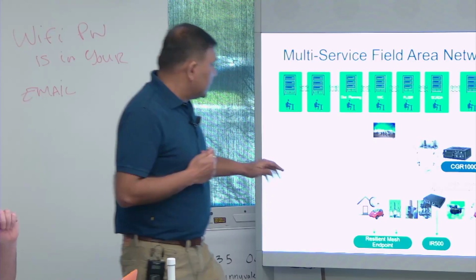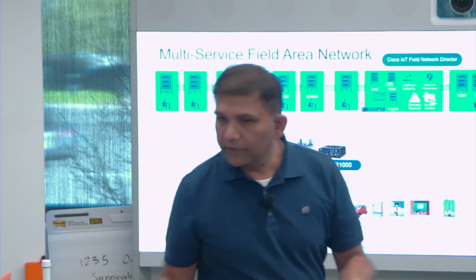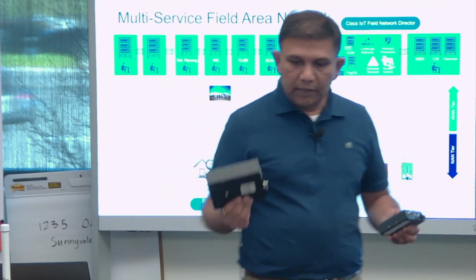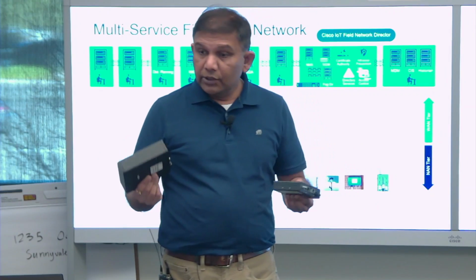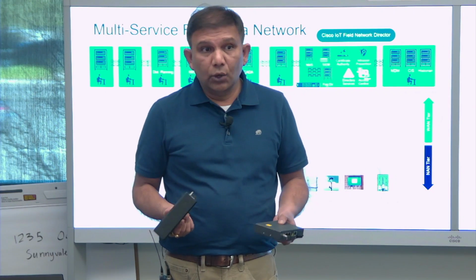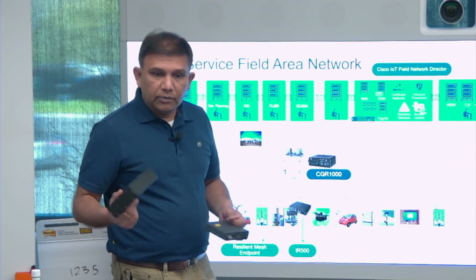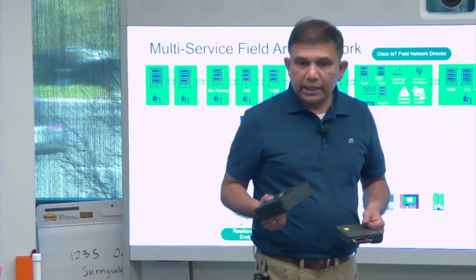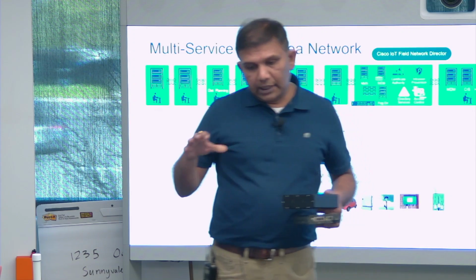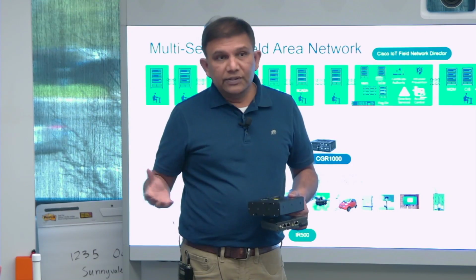So the other type of endpoint, and you have one on the previous version, the IR509 and the IR510 here. These are built by Cisco. They are to address the distribution automation use cases. Distribution automation being basically your voltage regulators, volt-var control, capacitor banks. A lot of these distribution grid devices, 80% of them still use serial connectivity.